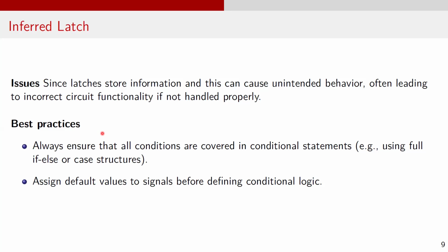To avoid inferred latches in the design, we can follow a few guidelines. As a best practice, while writing RTL code, always ensure that all conditions are covered in conditional statements, for example, when using if, else, or case structures. Assign default values to signals before defining conditional logic. Taking care of these points while RTL coding, designers can avoid unintentional inferred latches during synthesis.